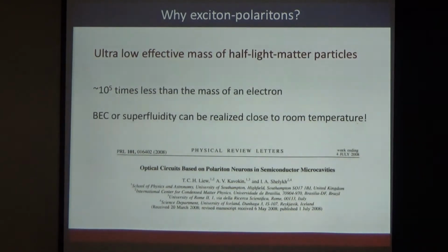Now we use this material, which has even better promise in terms of temperature, because it has a binding energy of 0.55 eV. And in the case of quantum well structures, the exciton binding energy is of the order of tens or maybe hundreds of milli-electron volts at most.